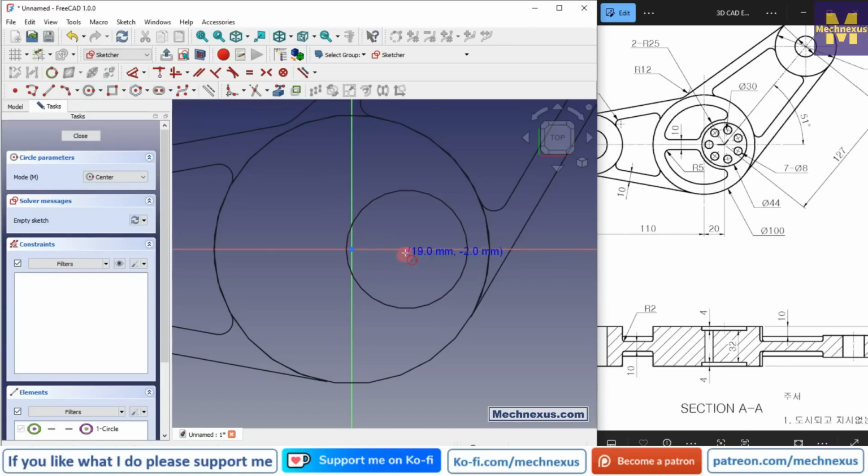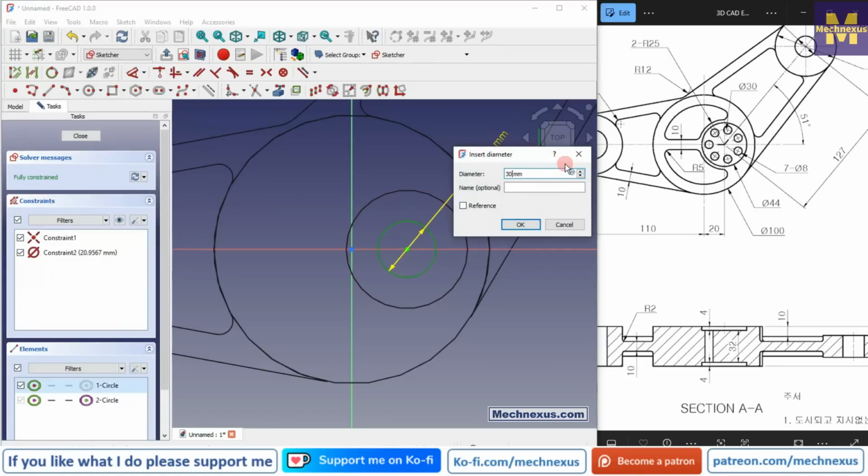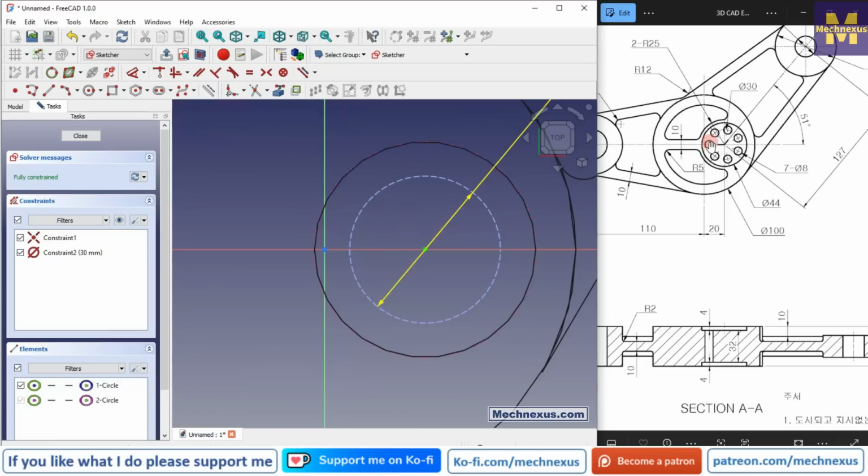So we will select a circle, select smart dimension, make it 30, and we will make it a construction because it is a PCD diameter.